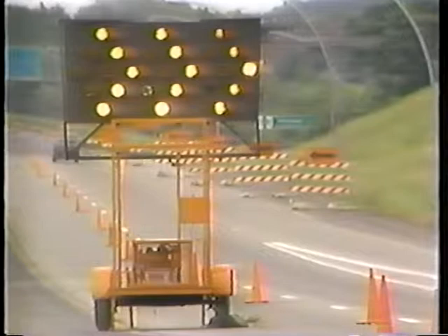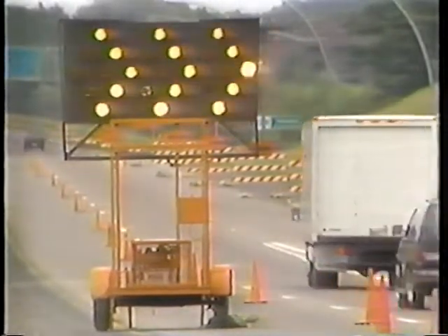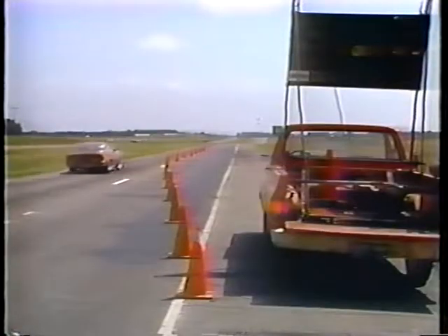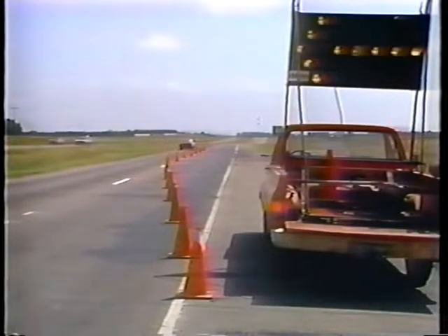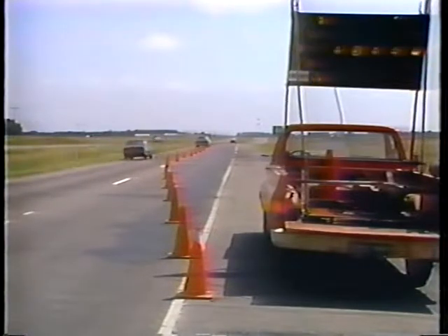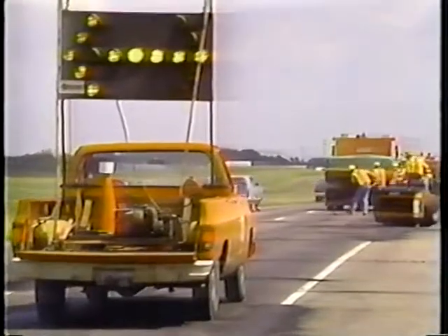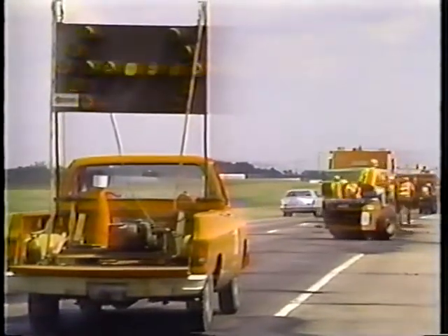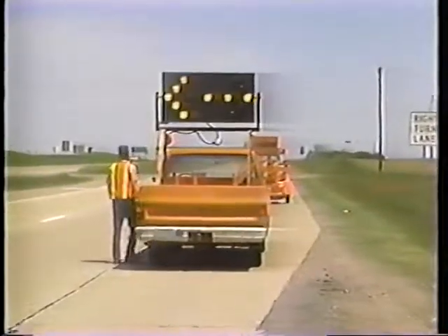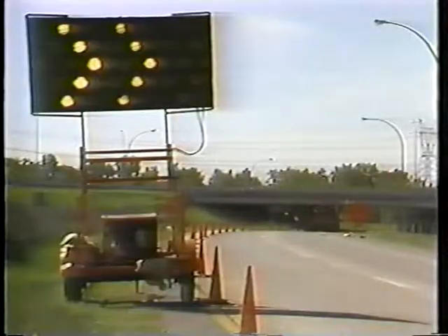Arrow displays are signs with a matrix of lights capable of either flashing or sequential displays. They are used for moving traffic out of a lane and may be used at tapered lane closures and with mobile operations. They are not a substitute for a lane closure taper. There are two types of arrow displays: flashing and sequencing.